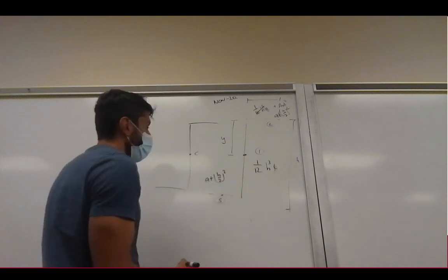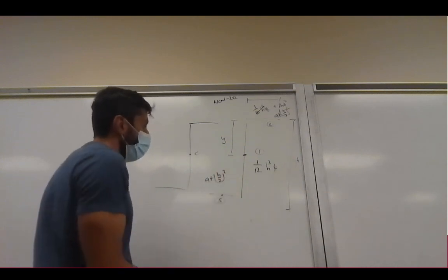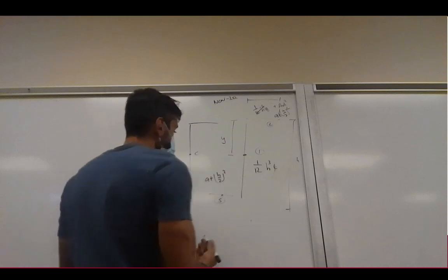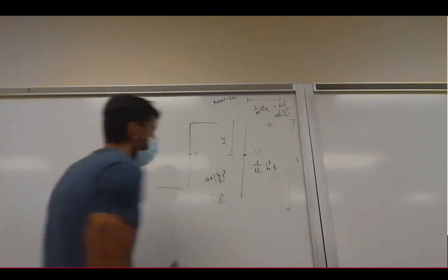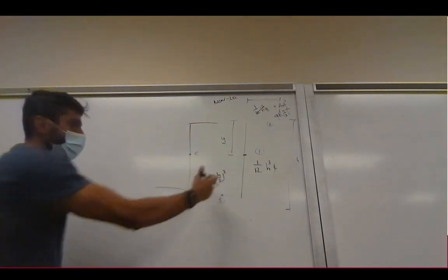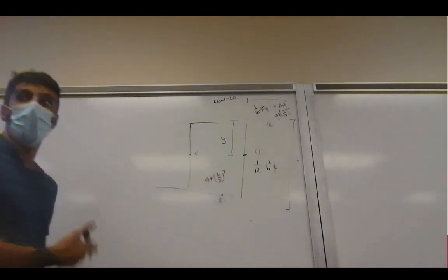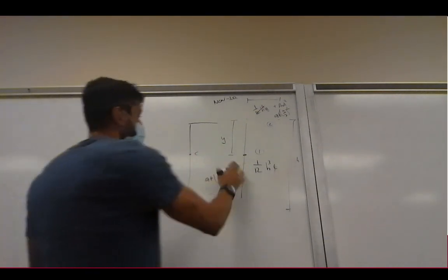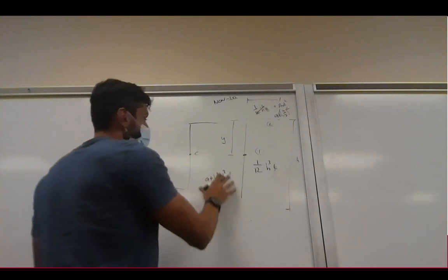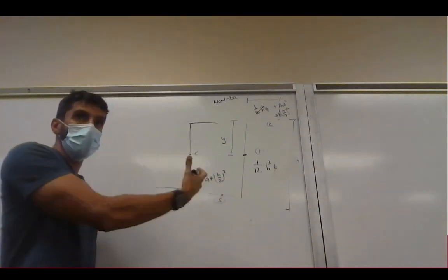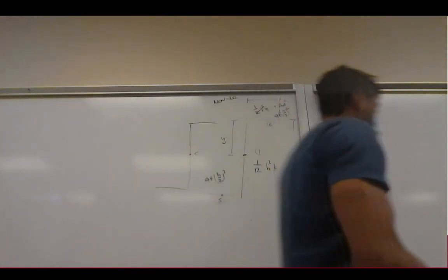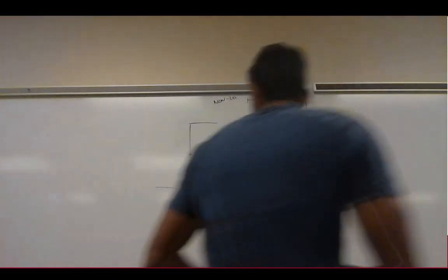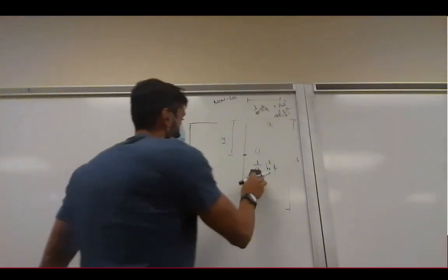And to be 100% consistent, you have to actually say it's minus h over 2, but because it's squared, this minus doesn't matter if you add it or not. So that's why, say with IXX, it doesn't matter where your coordinate system is, because the squares take care of it. So if we then look at the coordinate system of IXY,